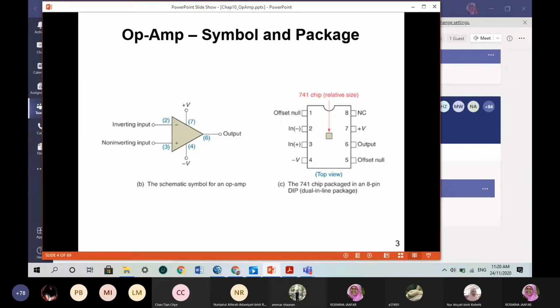As long as you do not apply a biasing voltage higher than the safe supply voltage, the Opamp will work normally in good condition. If you apply slightly below, your Opamp can last long. But you cannot apply a VCC that is too low. It has to be in the working range.